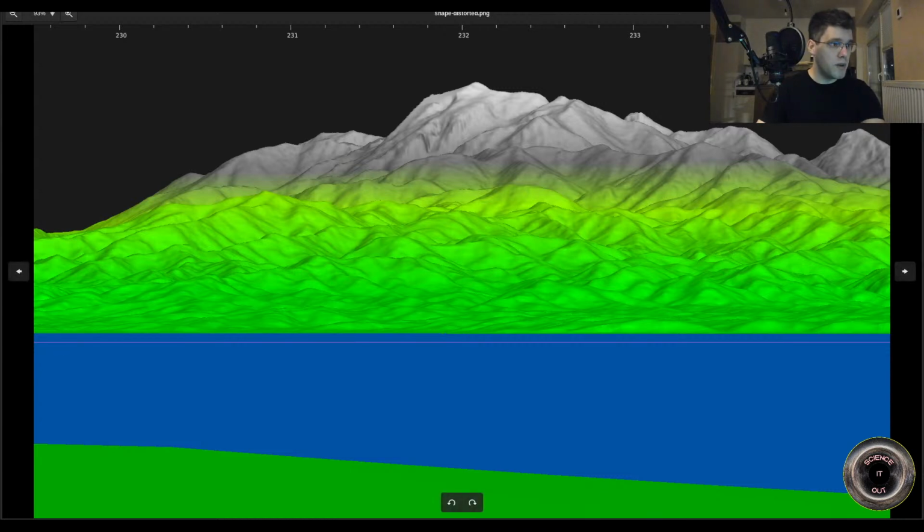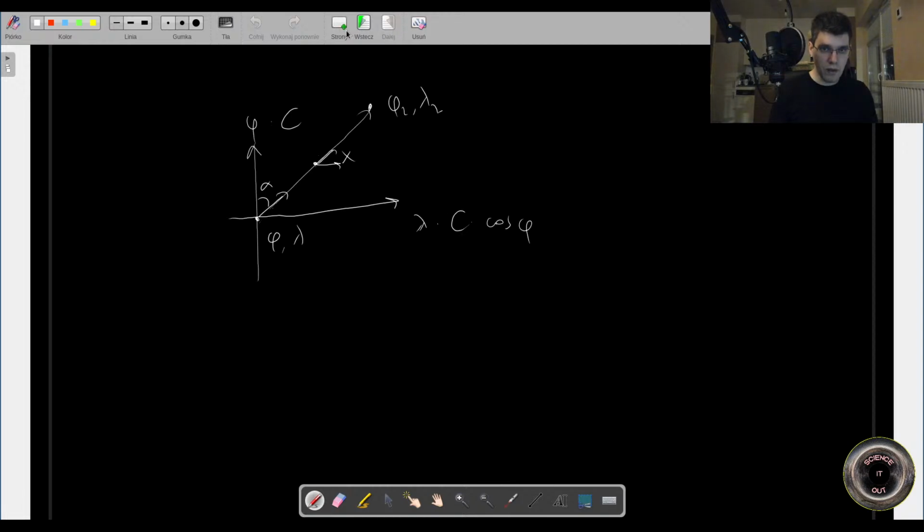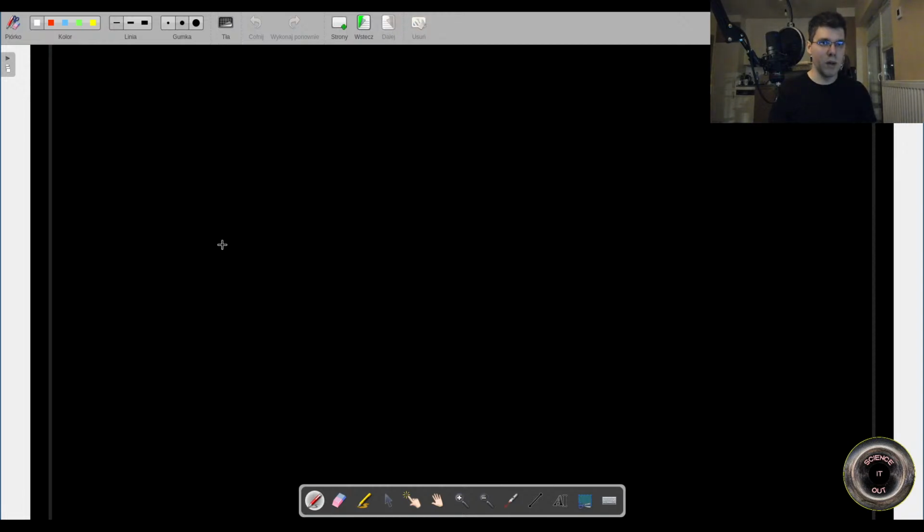So let's go to the third part, which is atmospheric model. And this part will be longer, and we are already almost 2 hours in, which is not good. Okay, so what I want to show you regarding the atmospheric model. What the atmospheric model does, really, it's a way of defining how pressure and temperature depend on altitude, and then this is recalculated by the program itself into the refractive index. So that's how you define refraction, really, in the simulator.